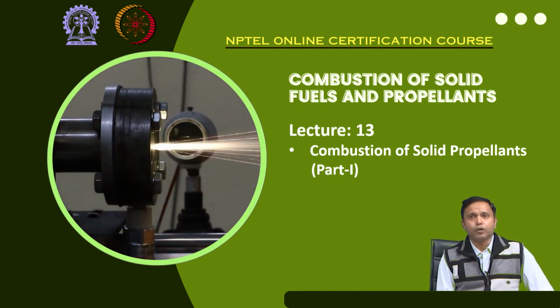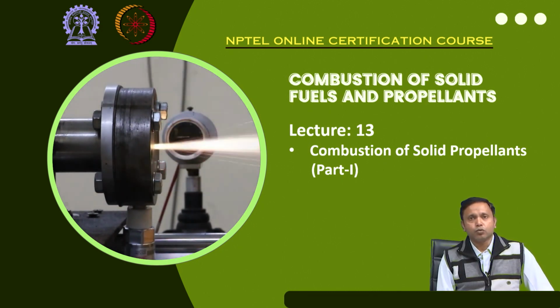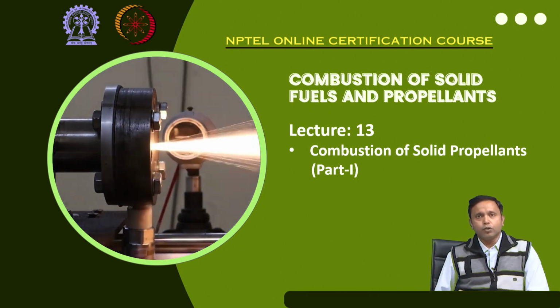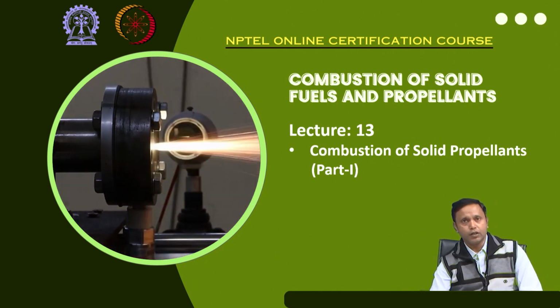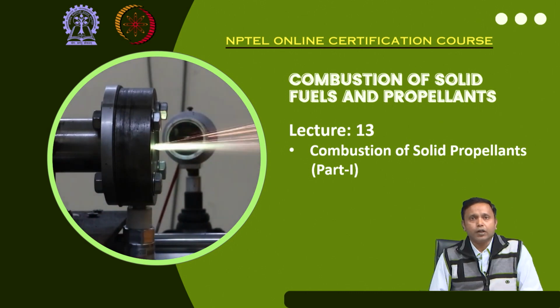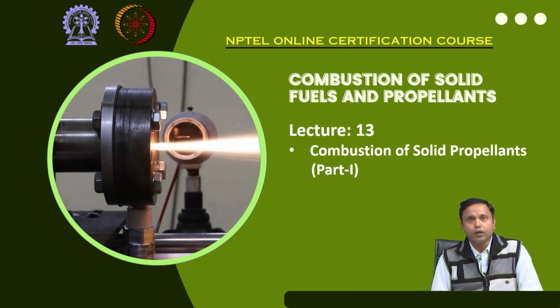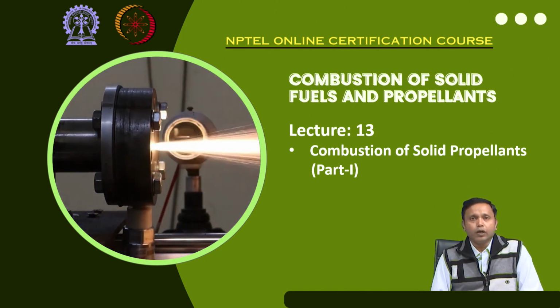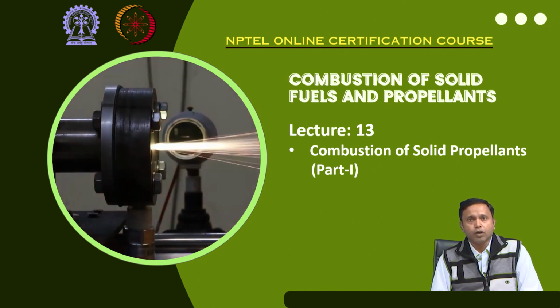From there, we will try to establish the burn rate law, which is very important in terms of combustion of solid fuels and propellants. In order to proceed further, we need to understand something in connection with the combustion processes, which is ignition. So we will also talk about the ignition processes, how the pressure increases over time during ignition, what the different types of igniters used in solid propellant rockets are, and then we will discuss the combustion processes of double base propellant and composite propellant in detail.